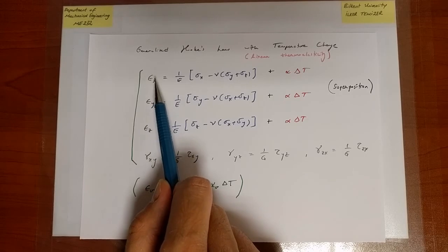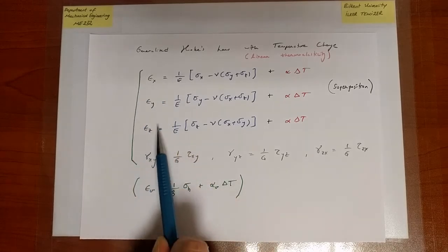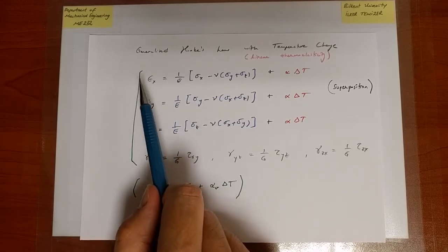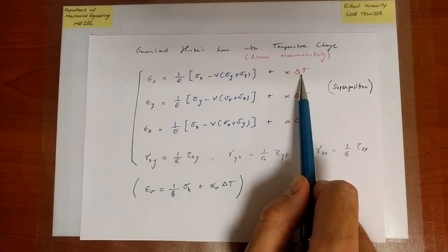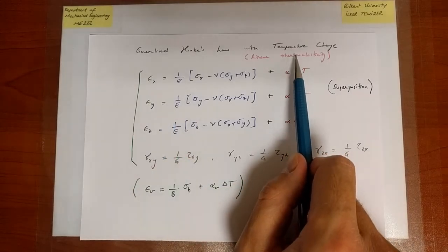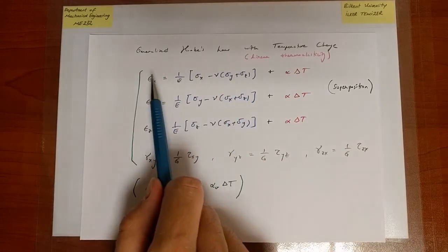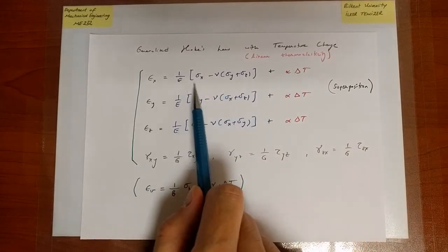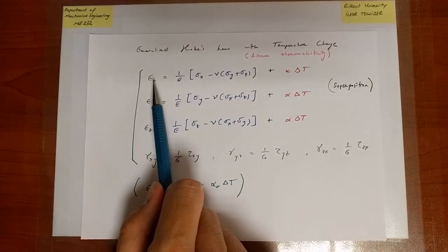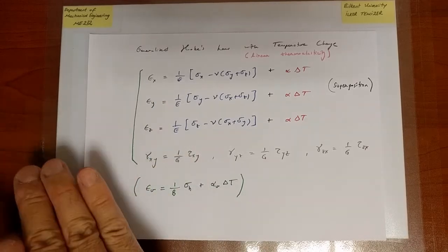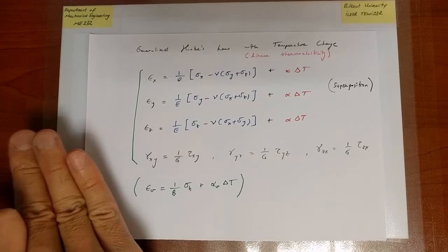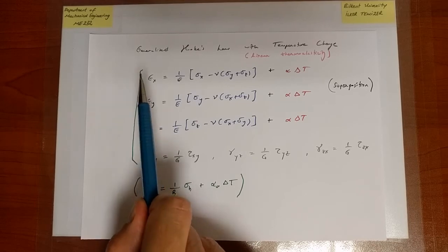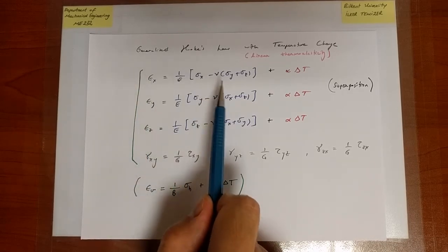So, in particular, if you have a structure that is constrained from expansion along its normal directions, then, well, if you heat up the material, and if alpha is positive, you will certainly end up having stresses, because if this is 0, and if this is non-zero, then there must be some terms here that balance that contribution to end up with a 0 value. So at this point, you should discard the strong notion that is embedded in your minds, at least in the context of linear thermal elasticity, that if you have 0 strain, you have 0 stress.